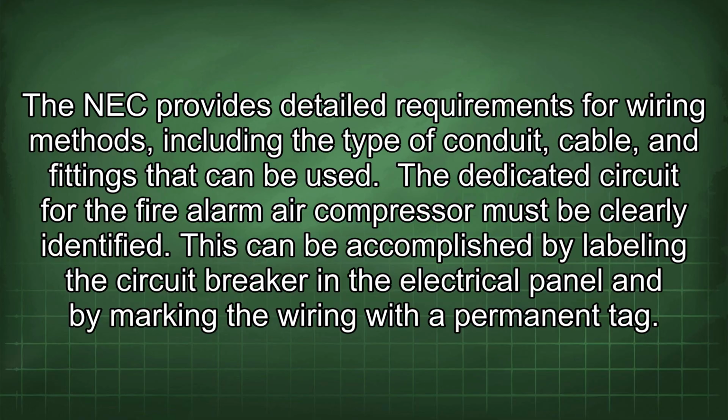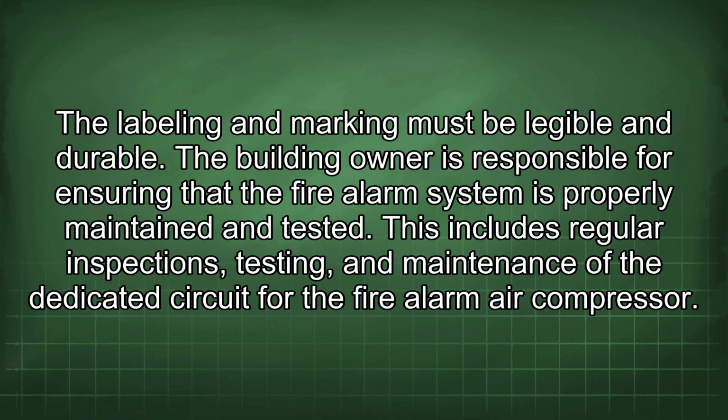This can be accomplished by labeling the circuit breaker in the electrical panel and by marking the wiring with a permanent tag. The labeling and marking must be legible and durable. The building owner is responsible for ensuring that the fire alarm system is properly maintained and tested. This includes regular inspections, testing, and maintenance of the dedicated circuit for the fire alarm air compressor.